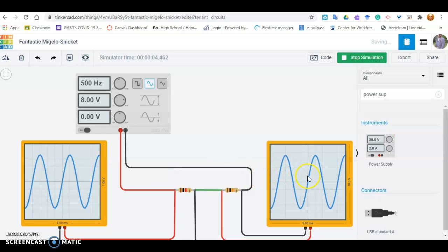You add those two together, 7.3 plus 0.7 gives us our 8 volt total that Kirchhoff's law said should be distributed in this series circuit. So you see that Kirchhoff's laws still do apply in our series circuit for AC circuits fundamentals, and our voltage is distributed proportionately by the resistor. We're able to read that on our oscilloscope here.